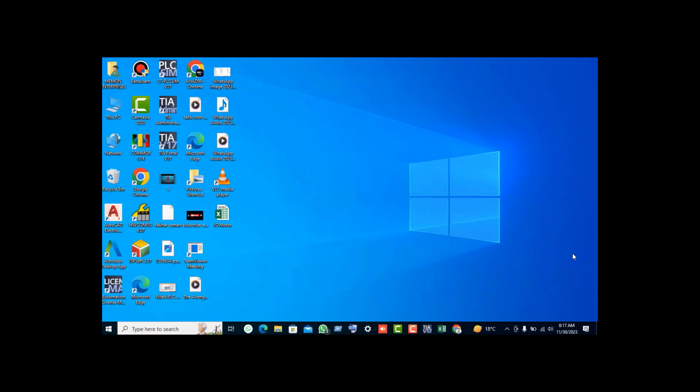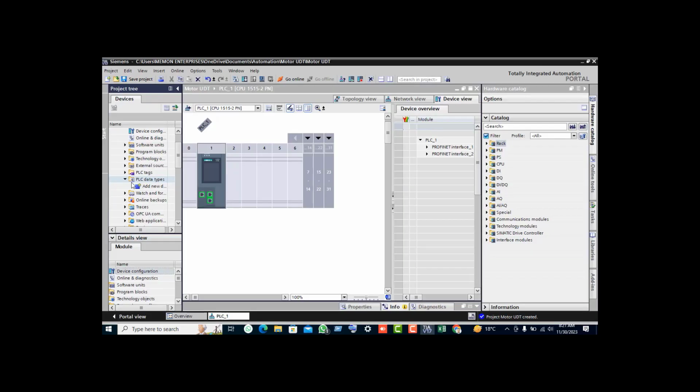Hello guys, today in this video I explain to you UDT, user defined tag. If in the industry they are running hundreds of motors and pumps on the same ladder logic, it is not necessary to write the same logic for each of them. Same like the tags, they are not required to be produced each time. We produce these tags once in data type tags and utilize them for all motors and pumps. So I show you how to use this technique.